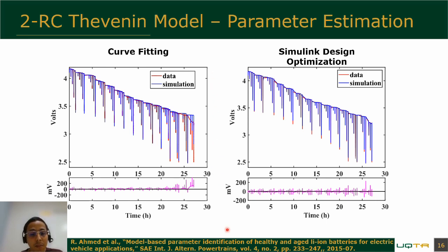The initial parameters obtained by curve fitting were used as a preliminary version of the final model parameters. Using Simulink Design Optimization to analyze each pulse, the initially estimated parameters can be refined. The reason to make an initial estimation is to avoid local minima and facilitate the optimization of the parameters when using the Simulink Design Optimization tool.